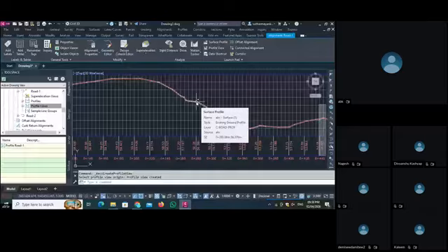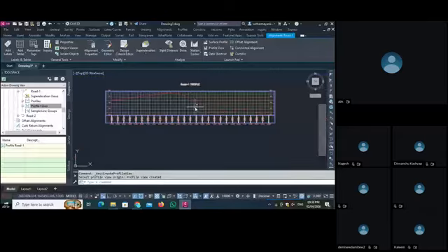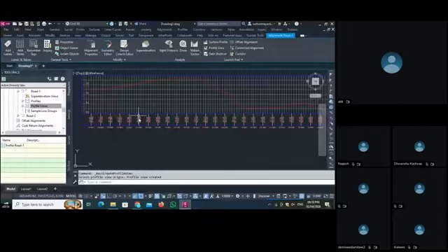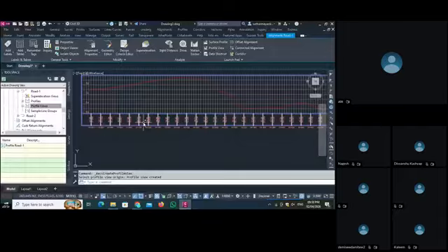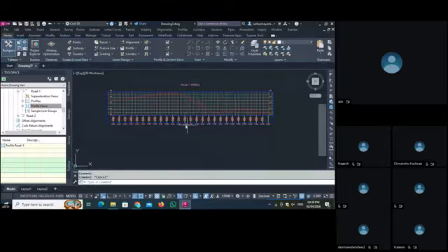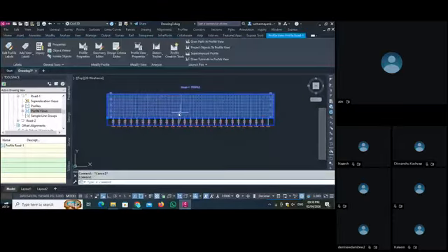When you put the marker on this red one, you can see your surface 1 profile. See, now below is your band set. When you select your profile view, you can see two things here. The first one is profile view properties, and the second is profile properties.